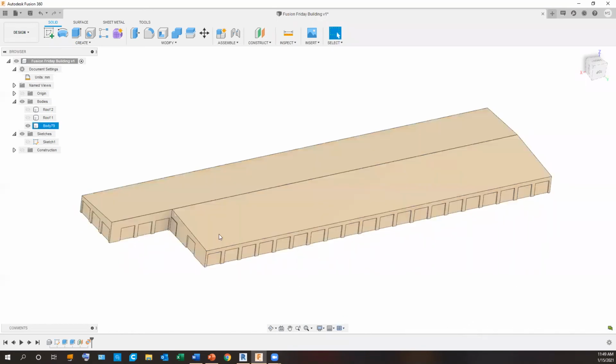Okay, so at this point, you've pretty much gotten it almost ready for 3D printing. Now you've got 3 options and you need to decide what you want to do with the 3D print. So you can actually print it as a single solid model with infill, like Alex was just saying. You can select a percentage of infill, so you could export it like this after you've scaled it down, of course. So you'll scale it down to a size where the entire model will fit into the volume of your 3D printer, and you can just print one full model. So that's one option. Another option is you can split the bodies.